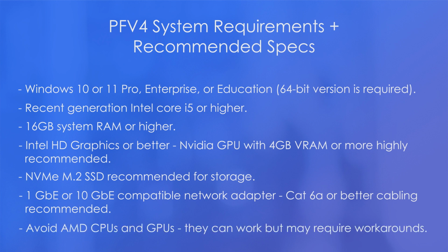Lastly, it's best to avoid AMD GPUs and CPUs. The PFV4 software is developed under the Intel platform and compiler, so it's recommended to stick with a full Intel environment. AMD PCs can and have worked with PFV4, but they may require workarounds to avoid affinity errors and crashes.